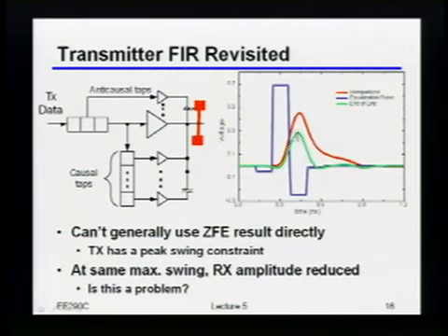If you compare the magnitude of this green pulse to that red pulse, which was the unequalized one, notice that after equalization the amplitude I get is smaller. If I kept the peaks the same as I used to have, then in order to do that equalization, my only choice is to make things smaller. To say it another way, in order to emphasize the high frequency stuff, I have to de-emphasize the low frequency stuff. By the way, when you put it on the transmitter, people will call it pre-emphasis or pre-de-emphasis or something like that. Does that make sense to people?